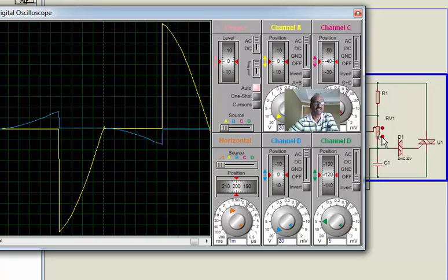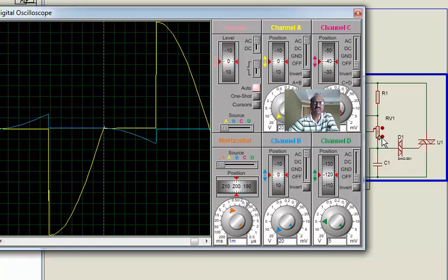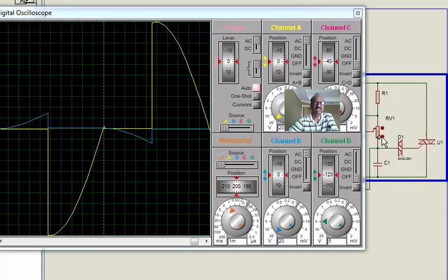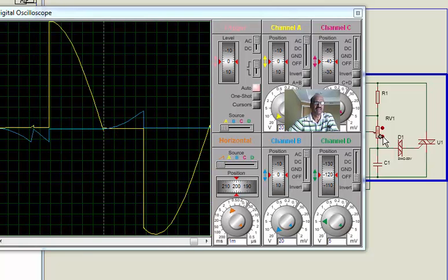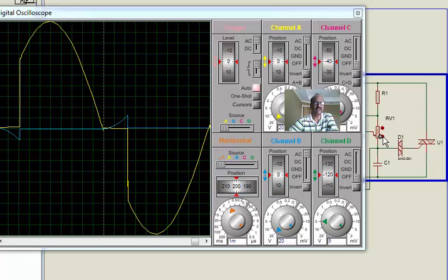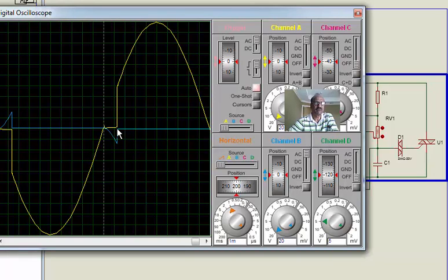Let's see it again. And once we come back with cutting the resistance, that means the C charges faster, in the sense earlier than the 5 milliseconds which we have noticed here. Now let's see, when we come to the full waveform, what we find here. What we notice is within about say 1.5 millisecond, it has reached 33 volts. Because it has reached 33 volts, this has triggered it. This is how the whole circuit operates.